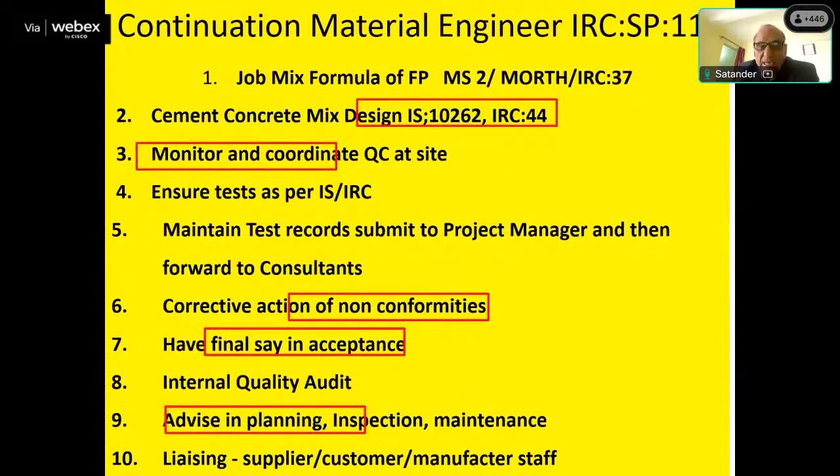Other main duties of the material engineer are how to do the job mix formula for the bituminous or concrete. He should know what the code provisions are. Now, in place of MS2, an IRC code has come, IRC SP 135 on bituminous mix design. In the revised MoRTH book, we have deleted MS2. Now IRC SP 135 is there. For concrete mix design, we should use IS 10262 for bridges and IRC 44 for rigid pavement. Monitor and coordinate the quality control at site. These are the duties of the material engineer.